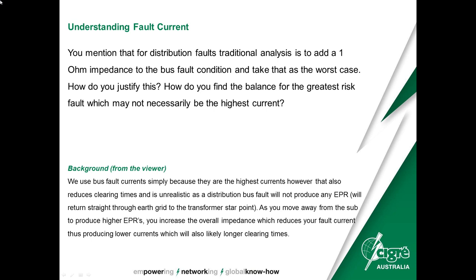Similarly for other criteria like for stressing telecommunications equipment or for pipeline interference. So I would say that the idea that I'll look down my feeders and get the worst case for step and touch voltage compliance is a good one. But even before someone started seeing that and thinking that through clearly, the documents published said we're just going to do the major sub. We're not looking at what's connected outside it. They probably were considering that what's connected outside it might not be there to start with, might change next year, next week, the year after. And so we can't rely on that so much as we can rely on the zone sub, and that there could be a worst case.